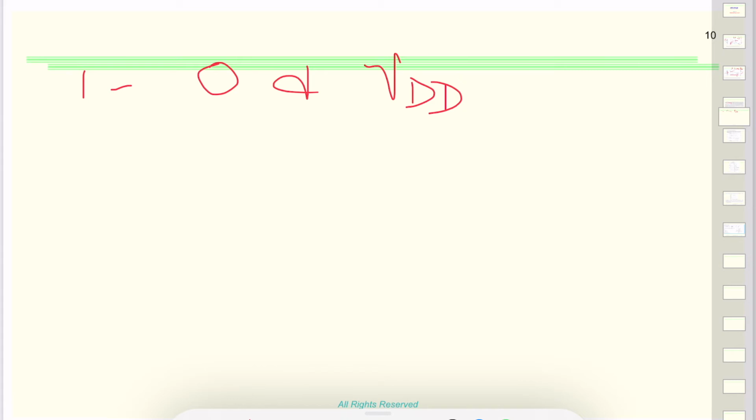So, and the signal swing is the maximum possible. And if we recall, we want that signal transition to be really fast with infinite slope, infinite gain. So from high to low, that's the signal swing which is maximum possible. So with QP and QN, it's possible that we can design to have a symmetrical voltage transfer